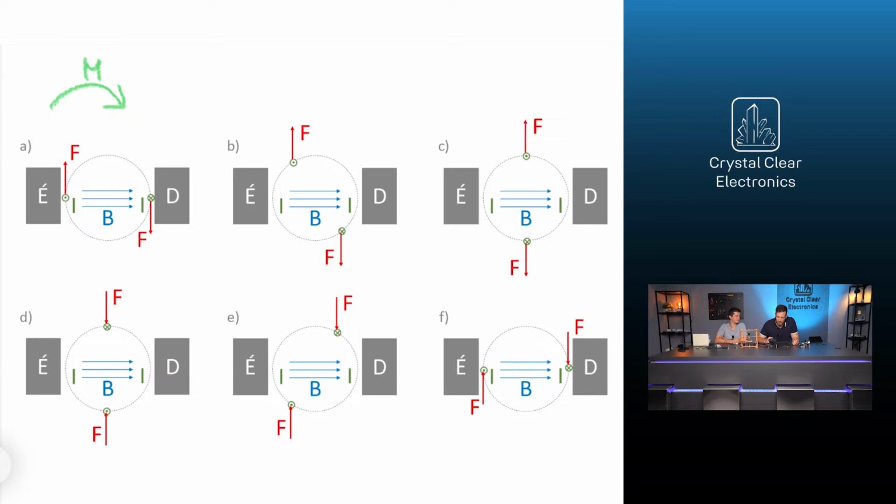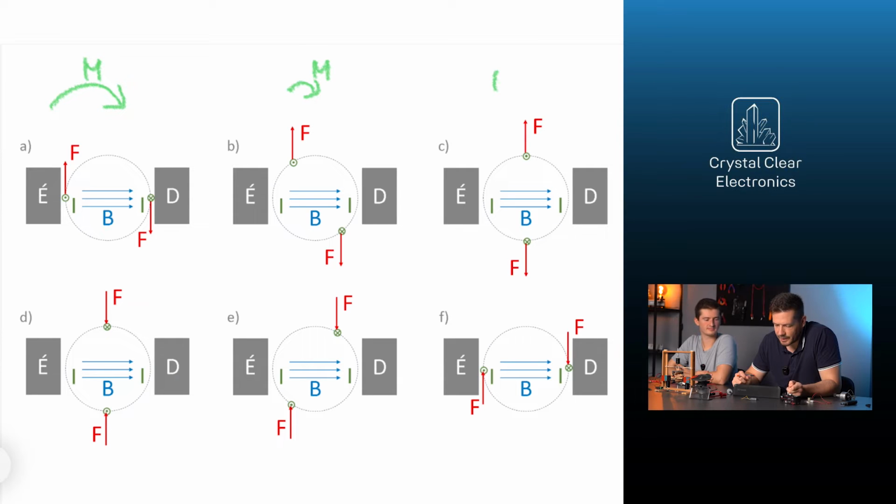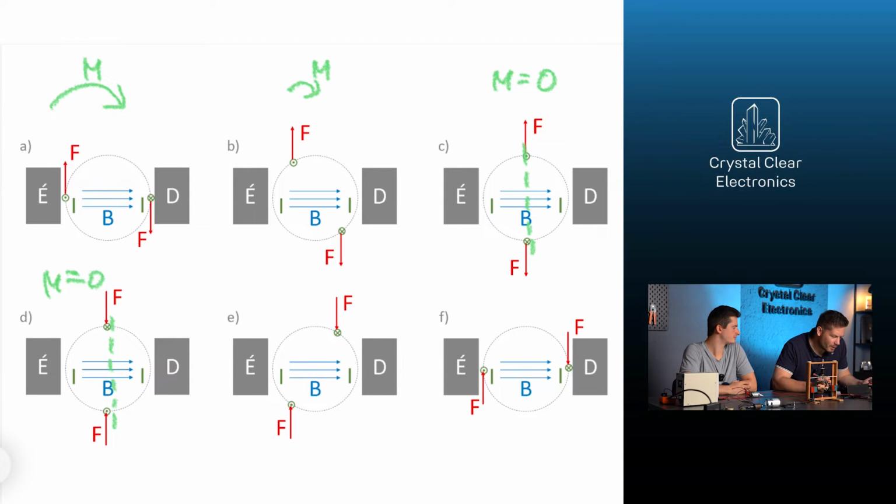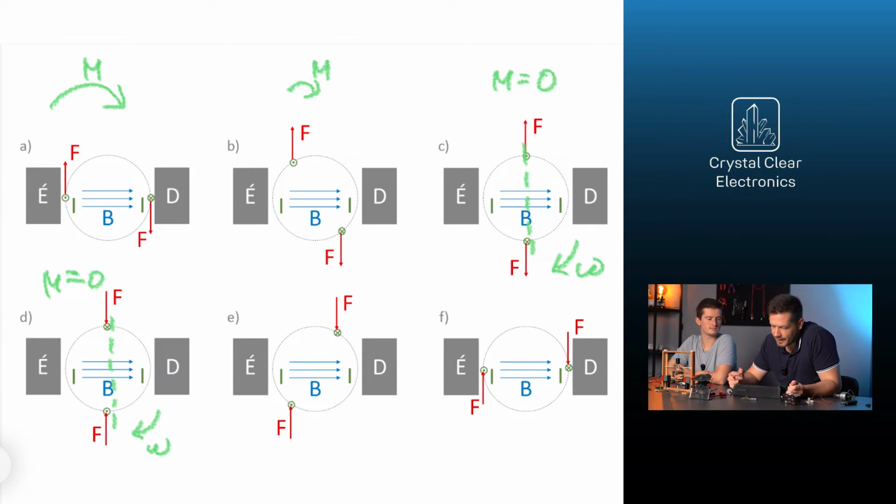The Lorentz force also has a similar effect on the conductor loop, up to the point where the forces on the two branches of the conductor are aligned. Here in the drawing, they are placed one above the other. Because they are of equal magnitude but in opposite directions, they cancel each other out, and no torque is created. If we leave the loop in this position, it won't be able to start from here. However, if it spins anyway, there is a chance of getting it through this point, but the problem is that the forces would start to slow it down.